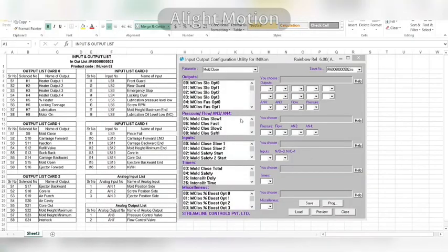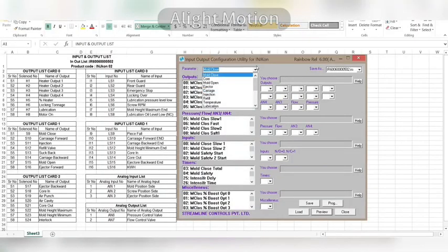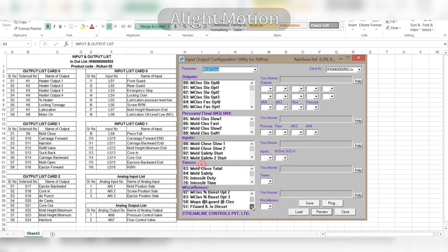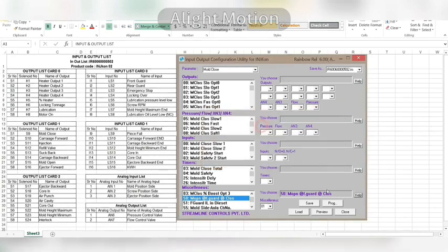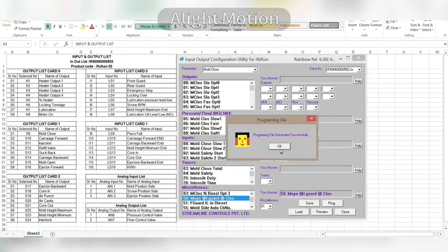You can see in the program each and every parameter of different functions: output, pressure flow, input, timer, and miscellaneous. If you have any problem, with the help of the help box, you can know the description of that parameter. As an example, we have enabled parameter number 50 by 01. What is that parameter? Mold open at front guard at mold close. You can know the description of the parameter by clicking help. So this we learned: how to create a sequence program.